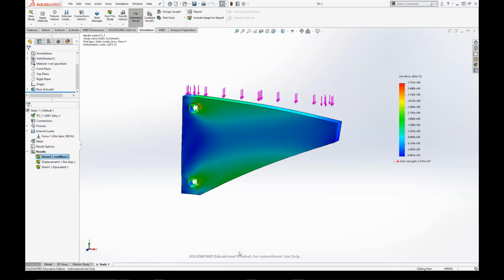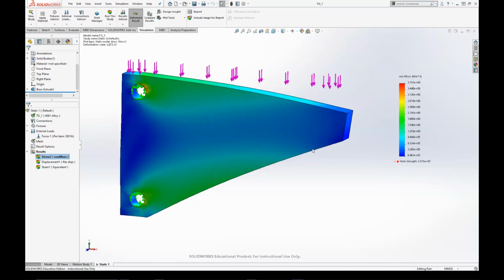If you have a block of material and you're subtracting the part out of that material, if the wastage of material is less, meaning the subtraction is less, then the manufacturing cost will be less. But in case of additive manufacturing, it is the opposite. If the weight of the material is less, then the manufacturing cost is less. So here I am going to optimize the weight of the part.